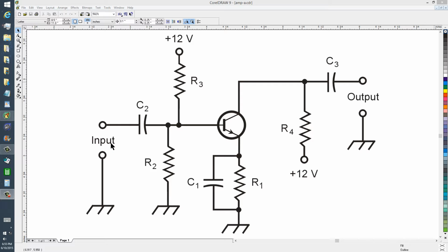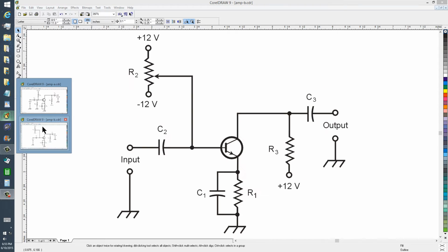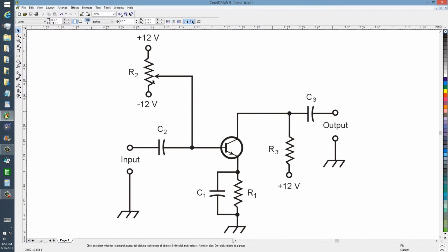Imagine that we put a sine wave audio tone of 500 Hertz here, an oscilloscope here at the output. Then we're going to see a 500 Hertz sine wave on the oscilloscope, assuming this is Class A. And that's it. We're stuck. We're fixed. However, we can also make the system more flexible by placing a potentiometer right here,